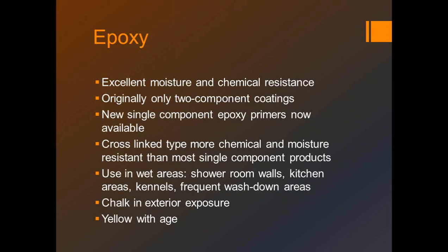I do want to underscore the value of using epoxy primers and using appropriate primers in surface preparation to go along with these finish coats. Block filler. That's a really good one right there. And the block filler is not just latex block filler. We do have epoxy block fillers. We have epoxy ester block fillers. We have cementitious epoxy ester block fillers that can do a really good job of waterproofing a CMU wall.